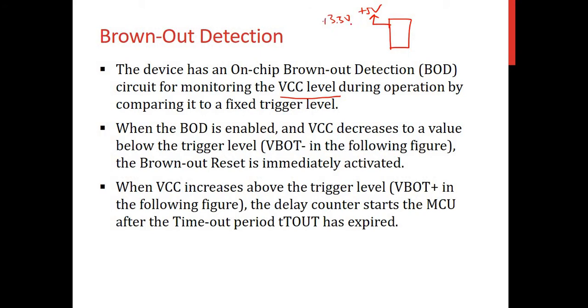Whatever is the case, we have to ensure that this voltage is stable. If there are fluctuations in the voltage level supplied to the microcontroller, the operation of the device can be compromised. So what we want to do is make sure that the voltage doesn't drop below what is acceptable to the controller, that is safe.